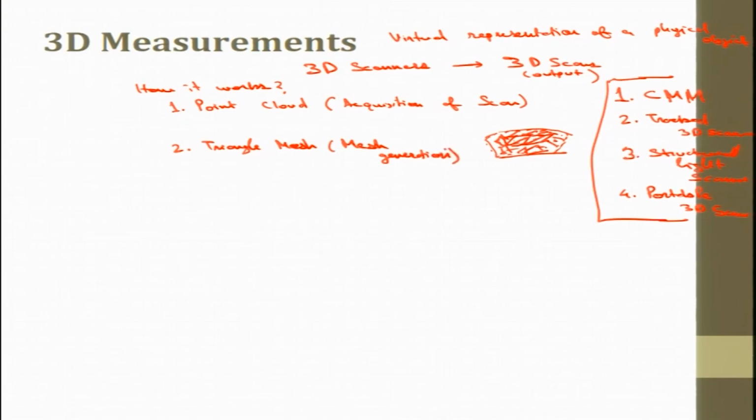The third step, when the mesh is generated, is that we need to optimize the mesh. There are a number of triangles, and when we conduct a strength analysis or heat analysis, this is the mesh. The more triangles there are, the more the computation. It depends upon what type of computation we need to do.